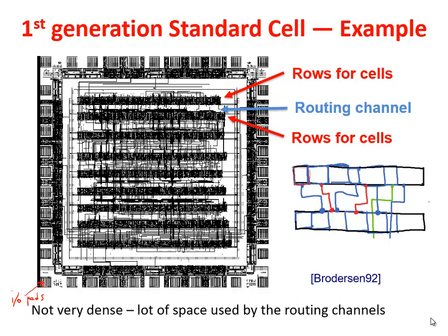And as you can see, it's not extremely efficient in terms of density, because you see that all the white space is space on the chip, which costs because it increases the area of the die, but does not provide a significant computing capability because there are only interconnections inside. Okay. But this is the typical situation in the 90s. So 20 years ago, a typical standard cell circuit was done like that.